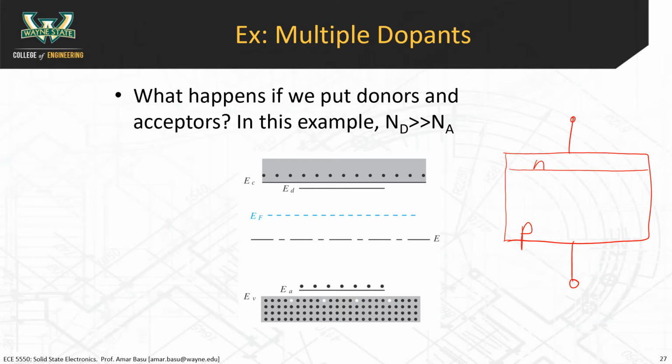You made a diode. The way they actually do this is that they start off with a block of p-type material that's been doped with boron, and then just the top of it you dope with a much higher concentration of phosphorus, a column 5 element. And you can actually switch it. If you add enough phosphorus, you can make it neutral. And if you add even more phosphorus, now you've changed it from p-type to n-type. That's the way they actually do it in practice.